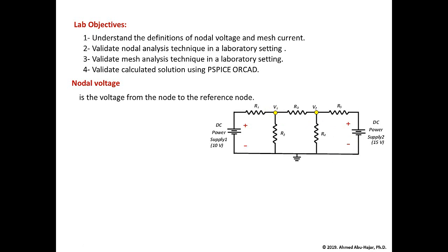The most important node is the node at the bottom here. This node at the bottom is basically what we call the ground node. It has this symbol. The symbol means that this node is physically connected to ground. In the laboratory, the power supply will have a ground node. We need to make sure that the reference node is connected to ground. We do that for safety reasons. So this is the first node, which is the ground node, but there is also 4 more nodes.